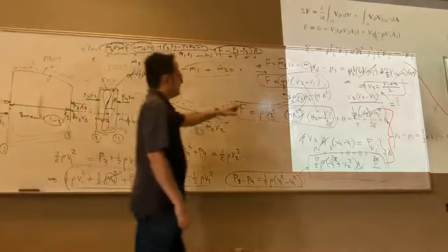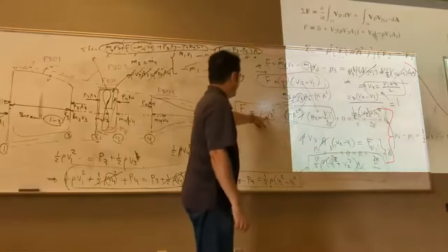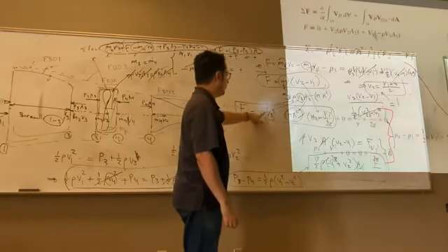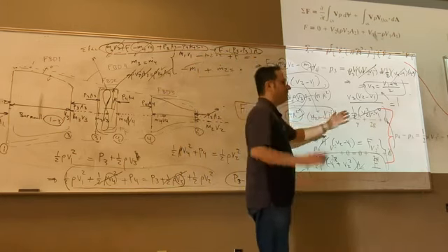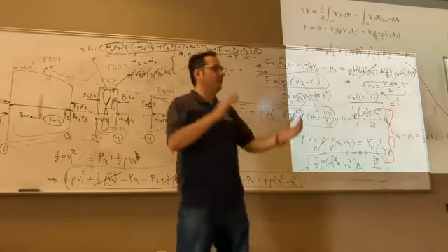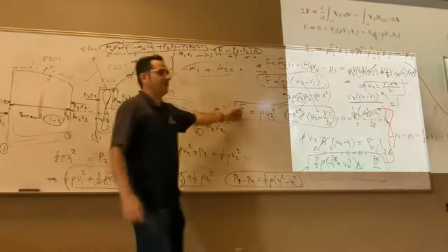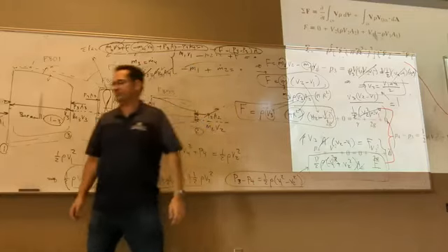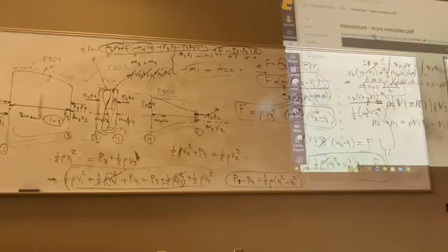So you get this V3, and then you substitute it in here for V3. You get thrust is equal to rho times 1/2 of velocity sum times the area times the velocity difference. So once you have the velocity inlet and outlet, you can find the thrust. That's what you're going to do in the lab.